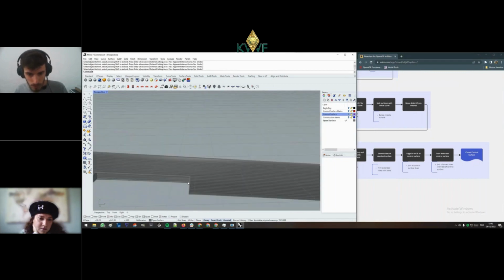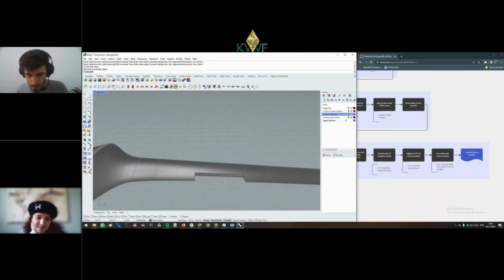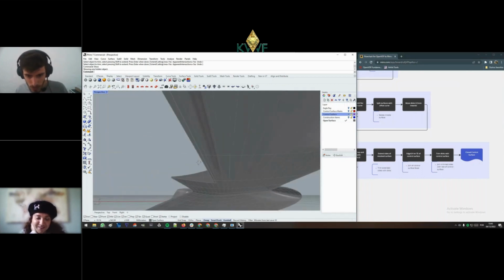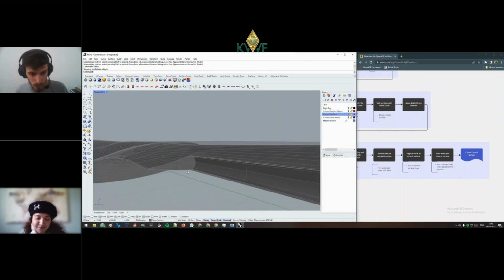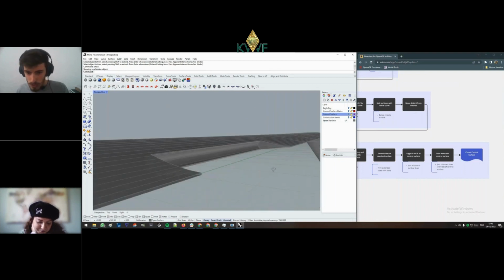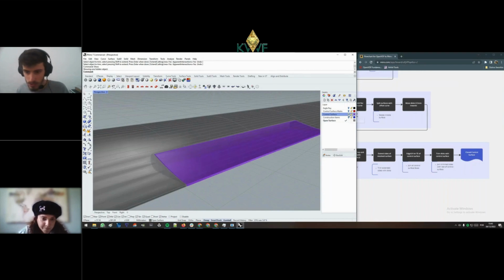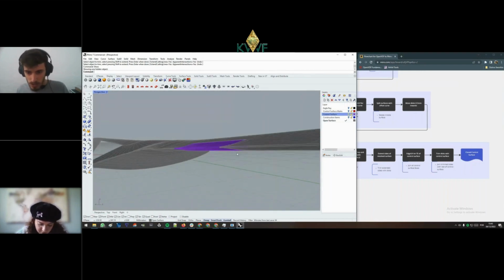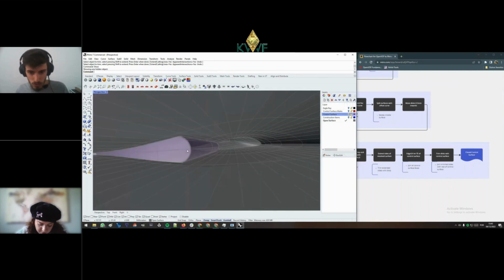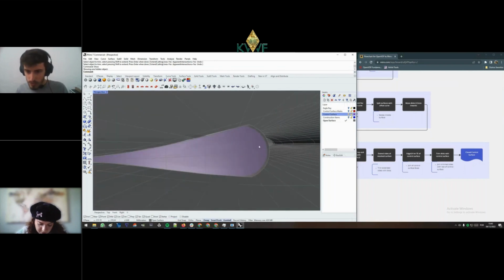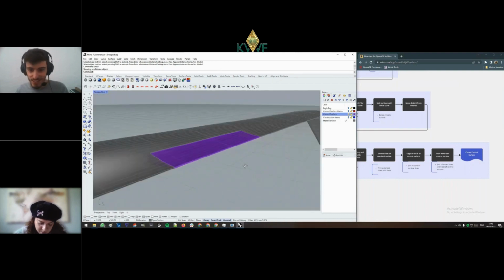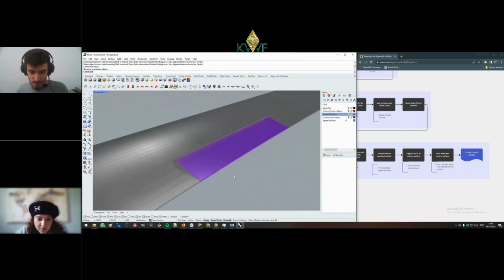There we go. Now I can show again the top surface, and we have a closed surface for the wing. So now the control surface can easily be housed in here, and it should be with the 0.5 millimeters clearance for the rotation. And I think that's it. That's the finished control surface cutting.